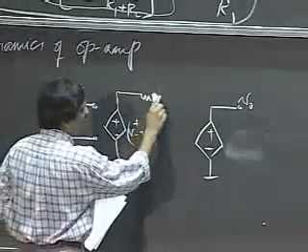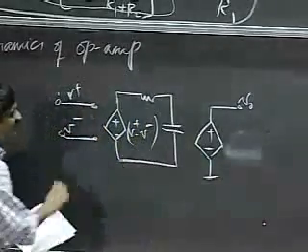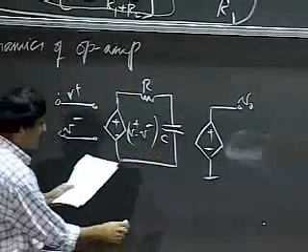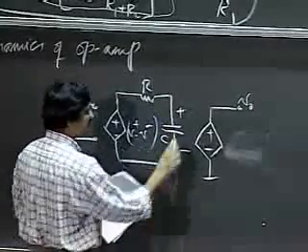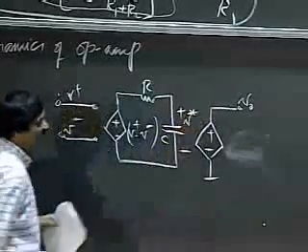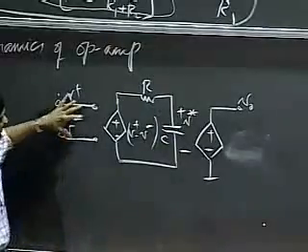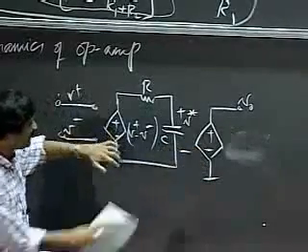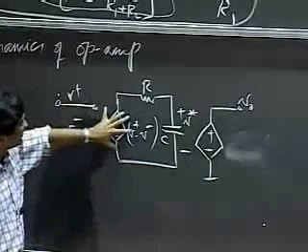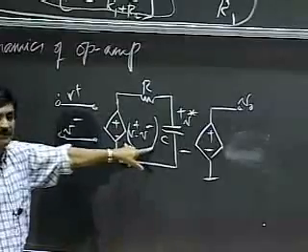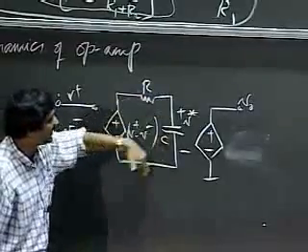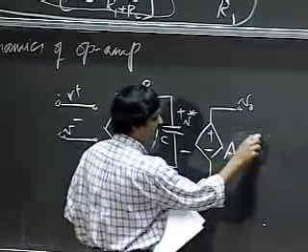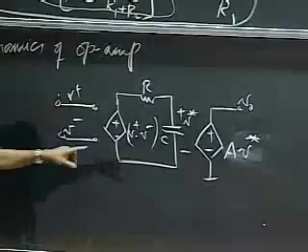So we're going to interpose a small RC circuit in here. This is R, this is C. And I'm going to call the voltage across the capacitor V star. So notice what I've done is, rather than say this is A times V plus minus V minus, I'm breaking it apart into two dependent sources. The first dependent source is simply V plus minus V minus, and there's an RC time constant surrounding it. And then here, I simply add on my gain, A V star.